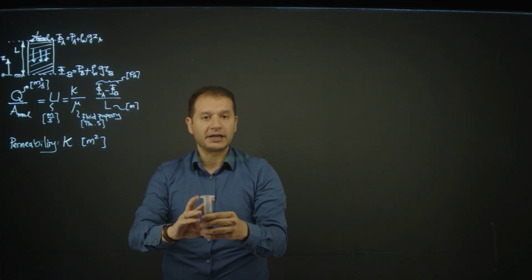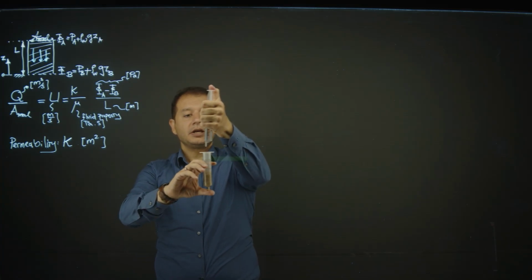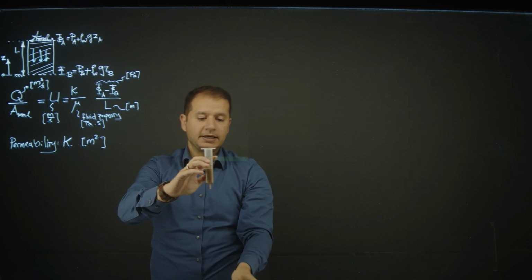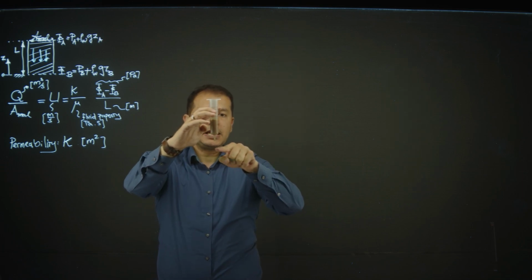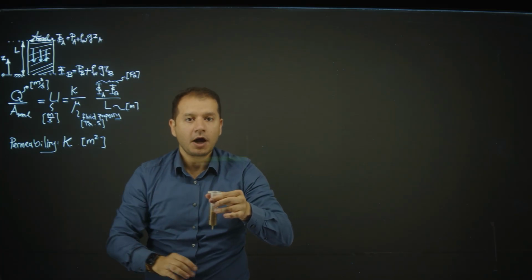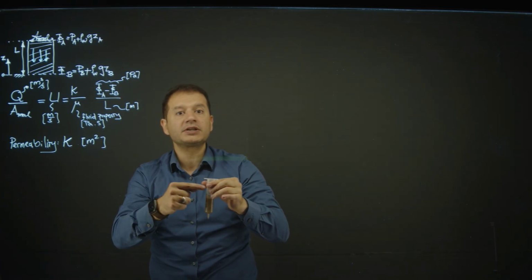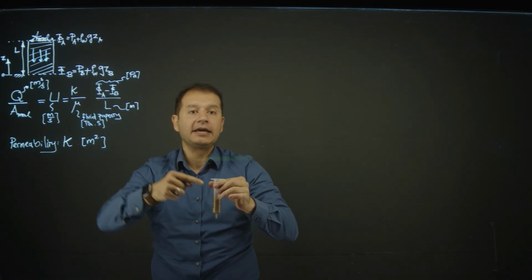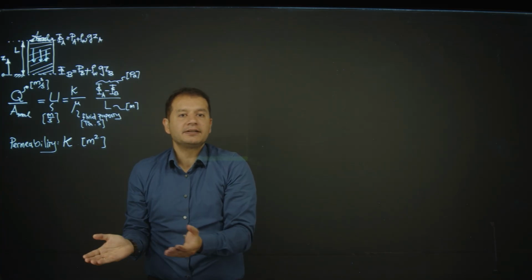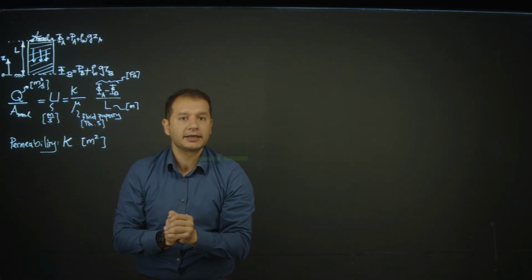in the first lecture. I'm not sure if you're listening to it the day after. And if I inject, for example, water on top of this sample, I can actually make flow happen. Do you see? I hope you see the droplets going through this. And if I want faster flow, I can just blow to make it go faster because I'm increasing the pressure at the location A for this sample. And I can measure the volume of water flowing through in a given second's time to find the flow rate and do the math to find K.